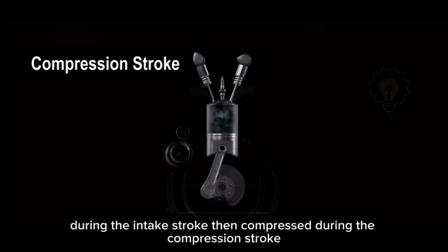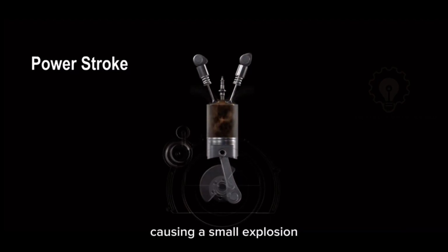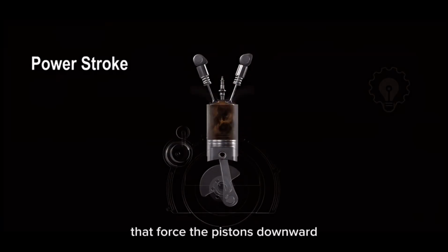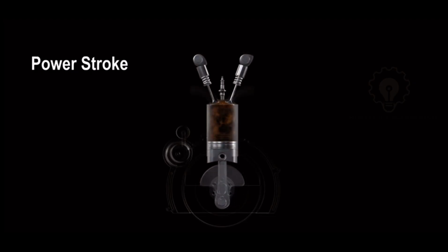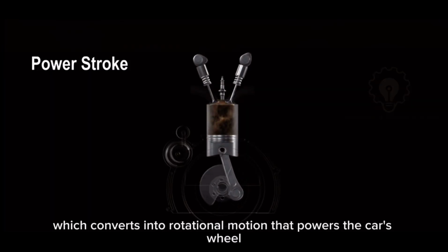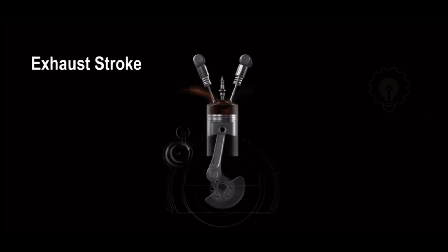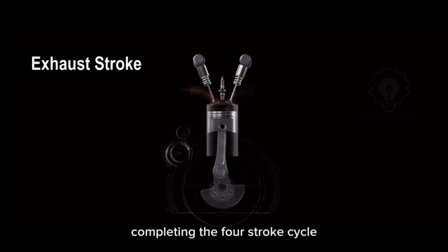then compressed during the compression stroke. A spark plug in gasoline engines ignites the compressed mixture, causing a small explosion. This explosion generates high-pressure gases that force the pistons downward during the power stroke, producing mechanical energy. The piston's up and down motion is transferred to the crankshaft, which converts it into rotational motion that powers the car's wheels. Finally, during the exhaust stroke, the spent gases are expelled from the chamber, completing the four-stroke cycle.